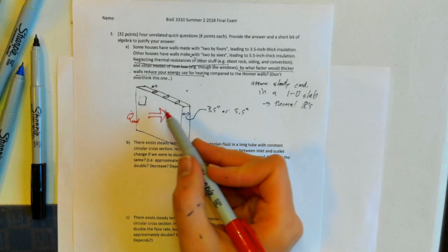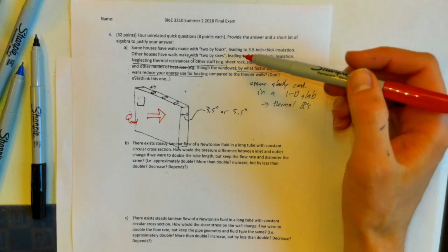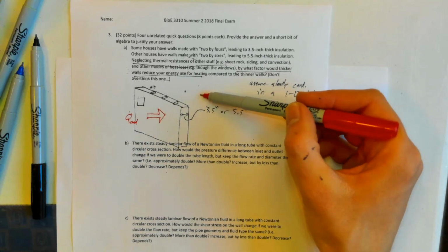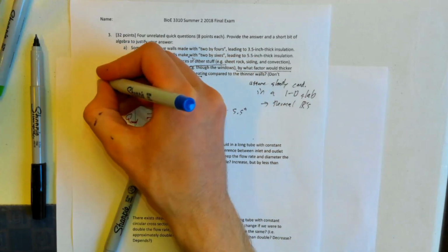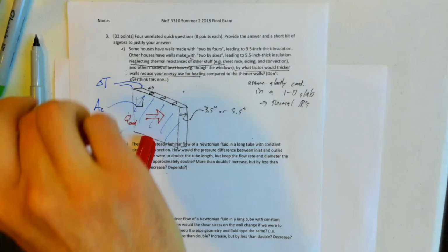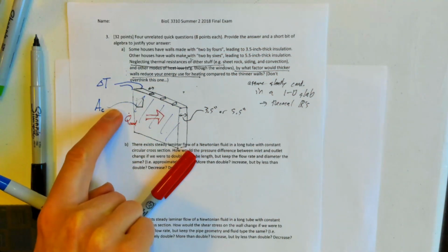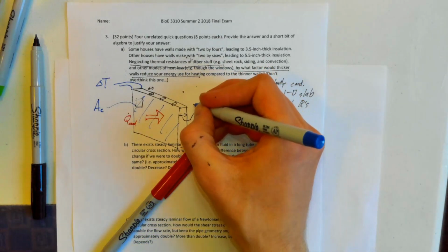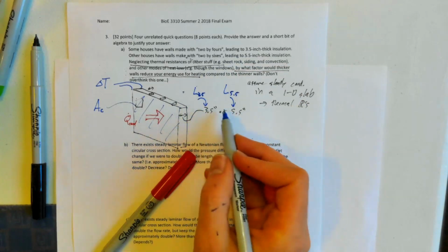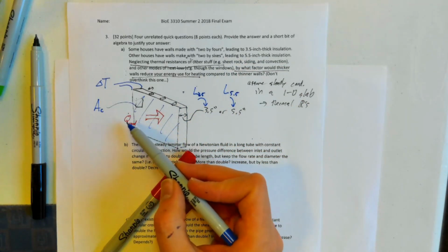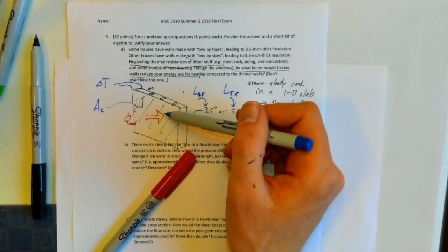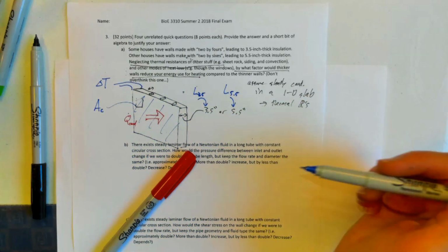And thermal resistances allow us to relate a temperature difference to a heat flow. So regardless of whether my house is made of 2x4s or 2x6s, I'm still going to want my inside temperature at some temperature. And the outside temperature is essentially dictated by the weather, right? So my delta T is something that I'm just going to take as a given. My cross-sectional area, the area that's normal to the direction of heat flow, is taken as a constant. So I'm just going to say that there's some L 3.5 and an L 5.5 that correspond to these two, and I want to ask what is the heat flow, the watts that flow through this wall? Yes, I'm investigating one wall here, but you could imagine scaling this up to all of the walls in the house and getting the same answer.